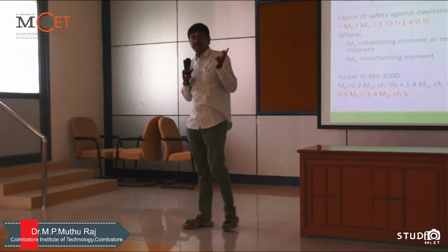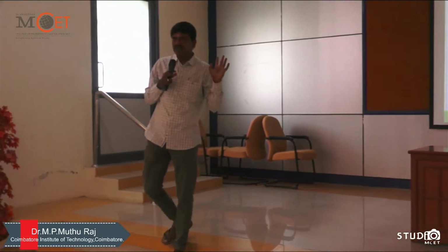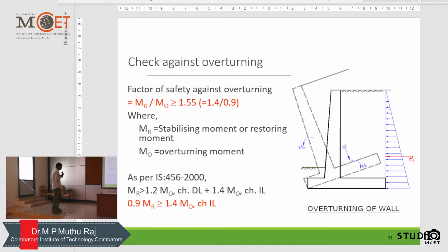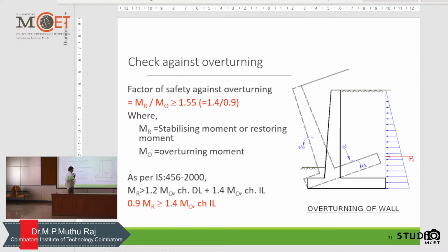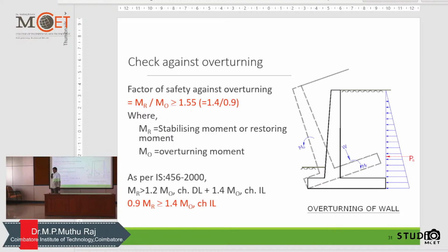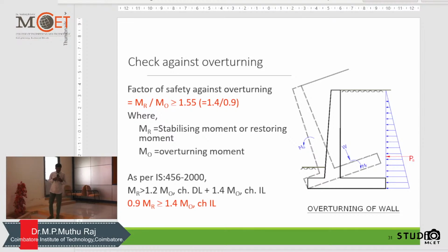There are two types of fabrics you can use, woven and non-woven. I think somebody might have explained it to you; later on we'll try to understand. So after understanding this cantilever retaining wall, next you have to understand where to start. In olden days there was no material available other than concrete to deal with the failure of this soil. What will happen? The soil will slide. So for this portion of the soil not to slide, we are introducing geotextiles or membranes. Several things are there that you can introduce.